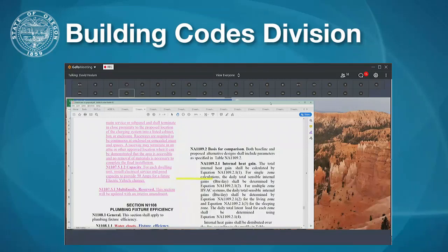And I know that the overall size of the panel gets factored at a lesser rate than the amperage of the actual branch circuit. So this is the amperage of the branch circuit. So when you're calculating the overall service panel size, it's less than this amperage, but this would be the amperage for the branch circuit. So just to clarify, when you size the breaker for the load, your breaker has to have additional capacity above that amp draw.